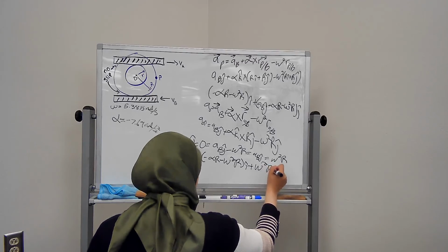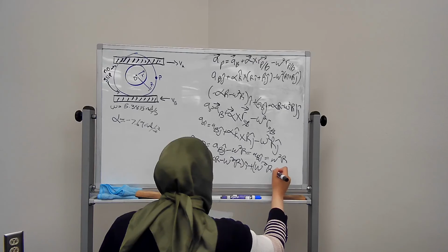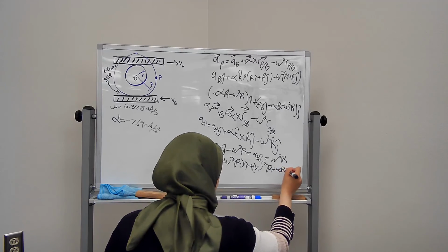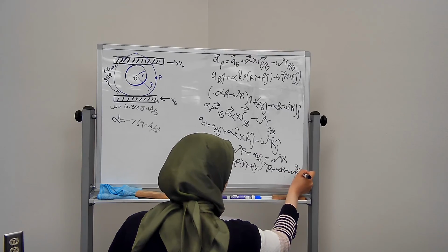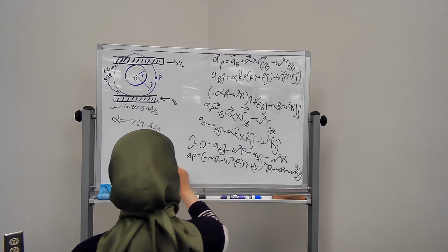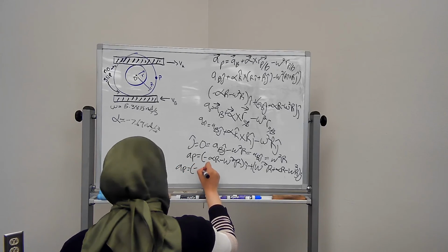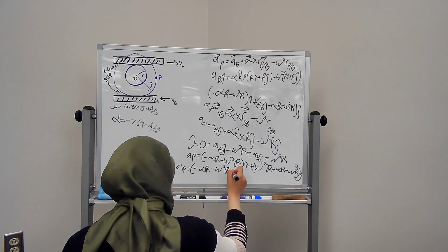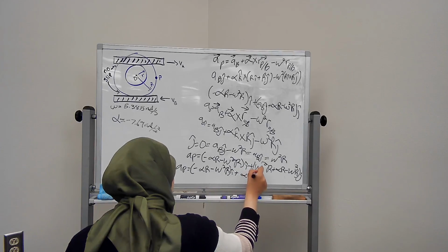Now that you know all of the variables for this equation, you can go and group it into its i and j components. So you would get that negative alpha times r minus omega squared times r in the i direction plus alpha times r in the j direction would be equal to your acceleration at point P. In doing so, you can go ahead and plug in all of your numerical values for this equation and solve for the numerical value for the acceleration at point P, and that would be the end of this problem.